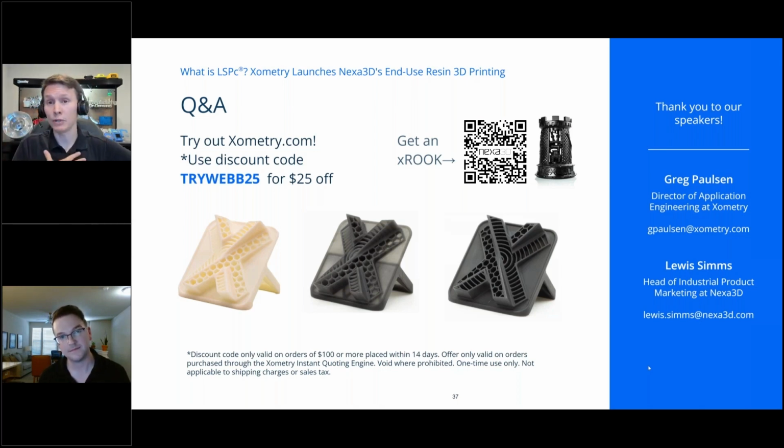And I do want to first, I'll also say on my side, part of our manufacturing standards, because this is kind of a DLP process, what we call the upward facing layers, or if you imagine downward, if you're thinking about build tray, we tend to have slightly looser tolerances on that for 2 reasons. So we usually have the overall part tolerances, and then those upward facing layers tend to have a 10 to 20 thou plus or minus wiggle to that for 2 reasons.